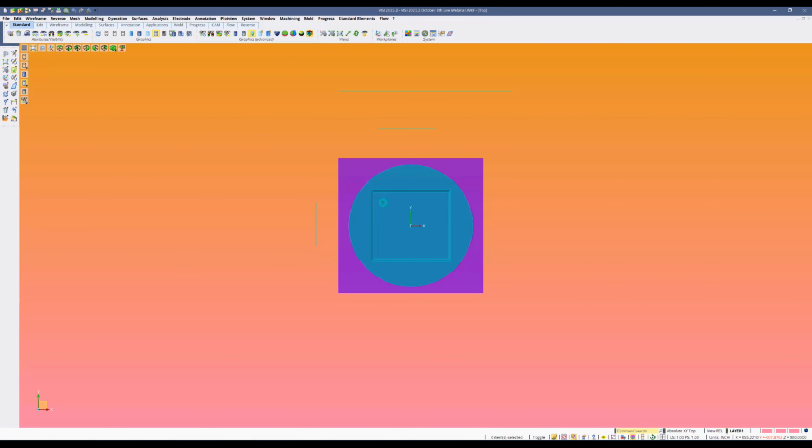And the third piece to this is we're going to go over the show number. And so what I mean by we're going to go over the show number is using the query static commands, there is a pound number that will be associated to each value. So like an X distance, Y distance, Z distance, there's going to be an actual pound number that is associated to each of those measurements, and we're going to show you how to utilize those pound numbers within a command in order to grab that value that it's representing. So let's go ahead and get into it.